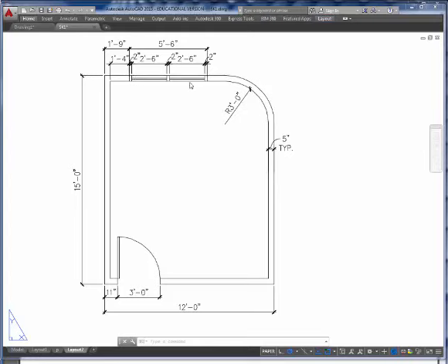There is a set of windows, 2 windows at the top, that it starts at 1 foot 9 from the outside face of the wall, and the opening, the size of the opening is 5 foot 6. The mullions are 2 inches by 5 inches, which is the thickness of the wall. The length of the window is 2 foot 6 inches. In AutoCAD, you can go the 2 foot 6 inches or 30 inches. We're going to see it in a minute.